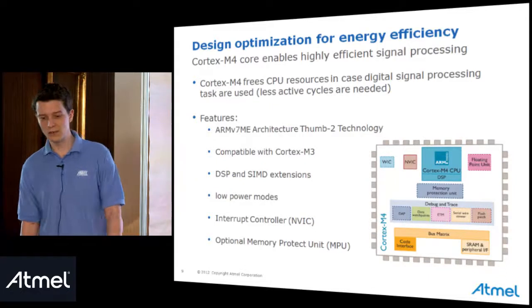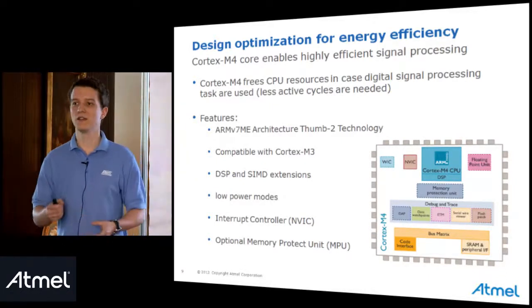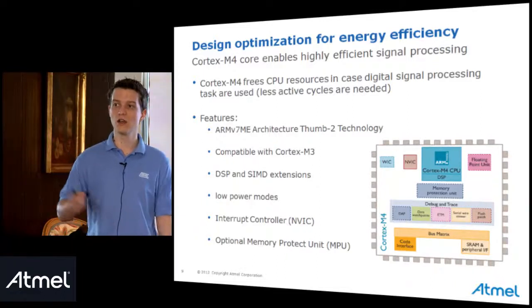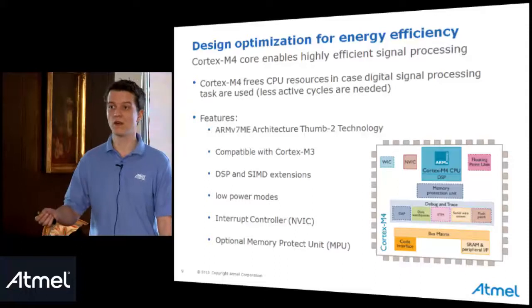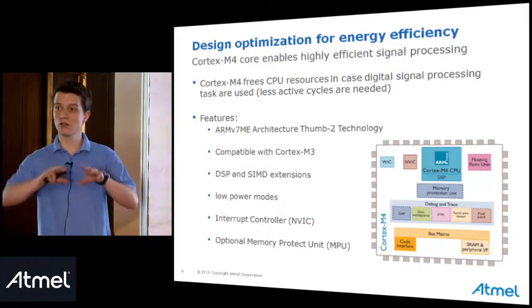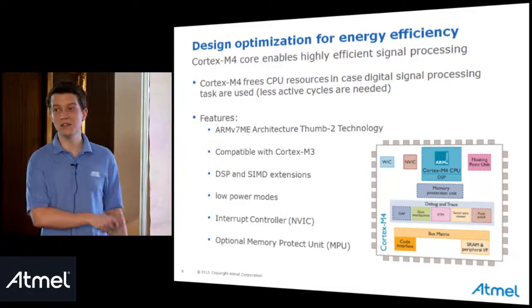When we say compatible, it means that all the software that has been developed for Cortex-M3 with specific core instructions is compatible with Cortex-M4. Cortex-M4 just includes what we call the instruction superset for DSP and SIMD instructions.